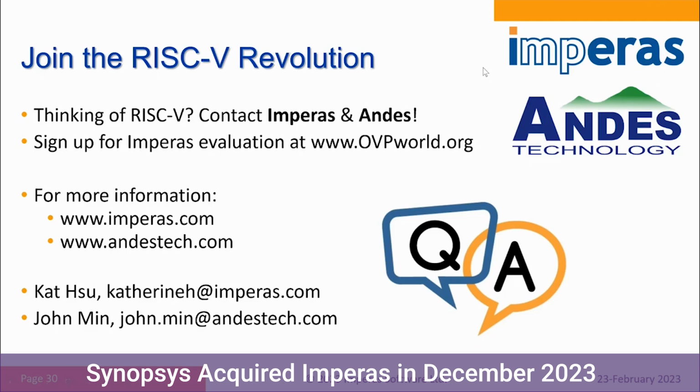Something that's different for Andes is you could create local memories, local states, and acceleration ports. So it's much more than just custom instructions. Tensilica actually, I believe, offers something similar to Andes in that they offer custom instructions, custom memories, and custom ports. So the ability we offer is all these capabilities for custom extensions on top of the standard RISC-V instruction set.